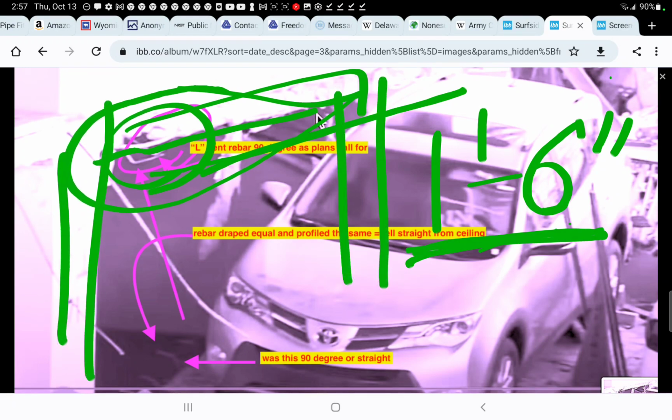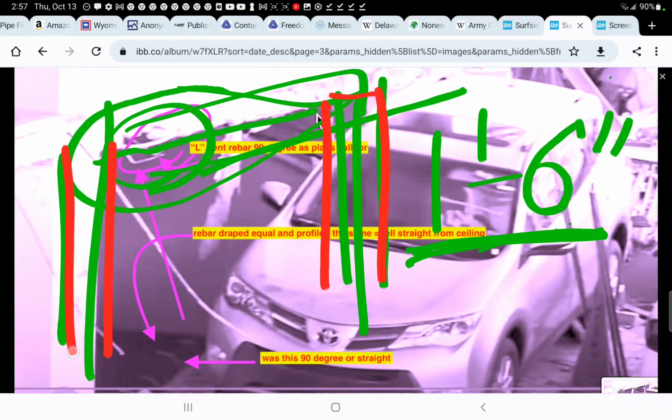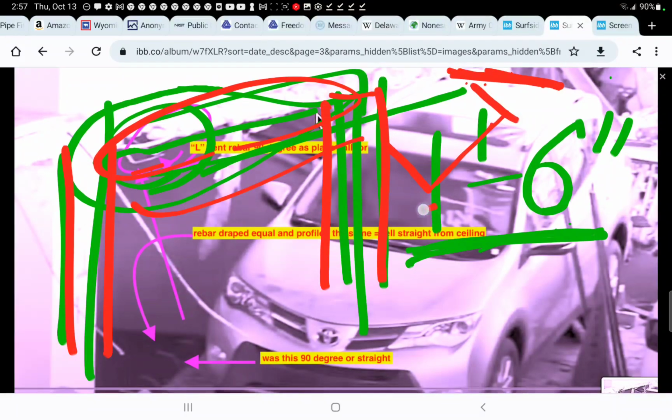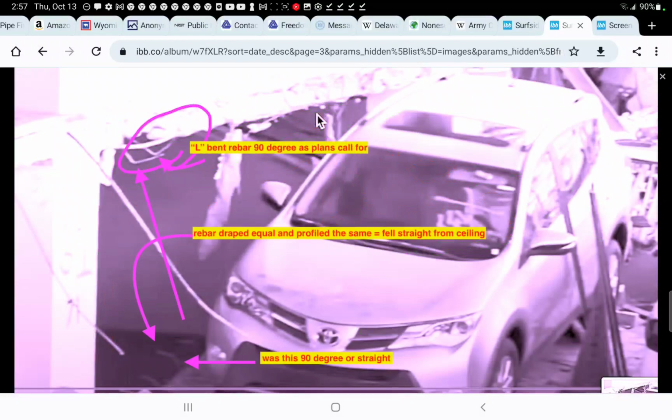The columns are here and here. There's a column behind this car. There's a column, short span, and yet this is what happened. And this is where that crack was, back here behind the car on the deck. There's a crack behind there, which leaves the planter box in place because the crack was preformed over time. Planter box, preformed crack. Preformed meaning the deck deflected some time ago and developed that crack.